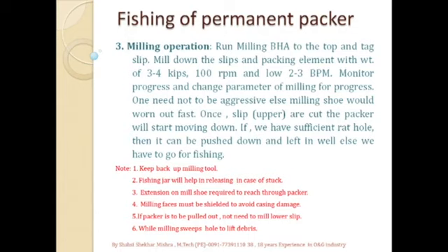And while milling, we have to sweep the hole to lift the debris to the surface and get collected in the junk sub. So once the milling operation is completed, we will circulate the well thoroughly at a high rate to make it clean, and all cuttings get collected on the surface or the junk boot.